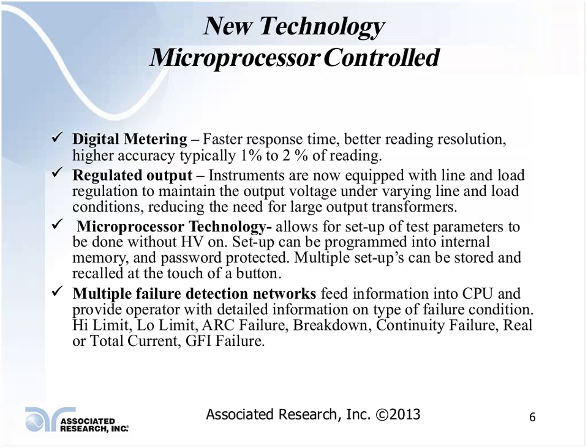One of the things with CTL accreditation is that they still go based upon accuracies of full scale. So actually, the accuracy of the equipment on some of the lower voltage readings and lower current readings is not as good, or is a much looser spec in regards to the accuracy of the equipment, with a CTL certification than with a 17025 accredited cal or a Z540.